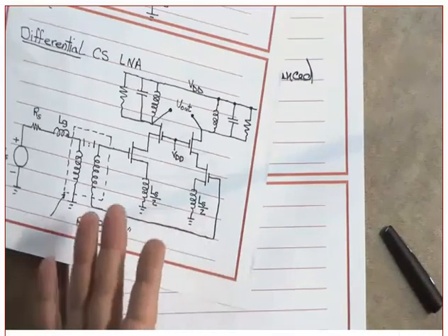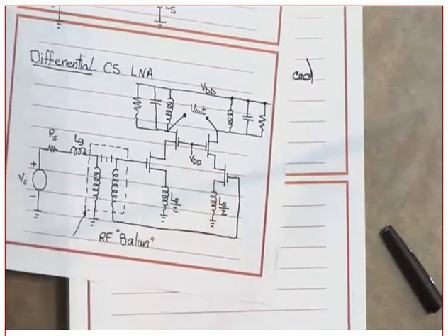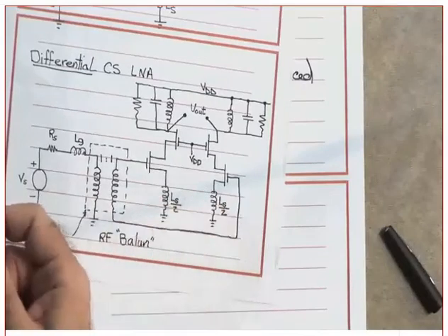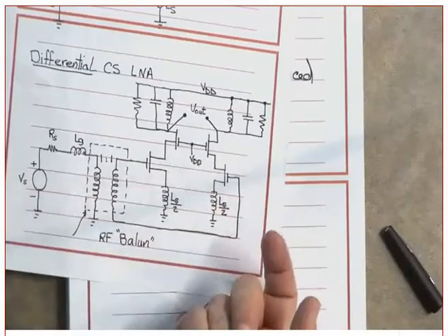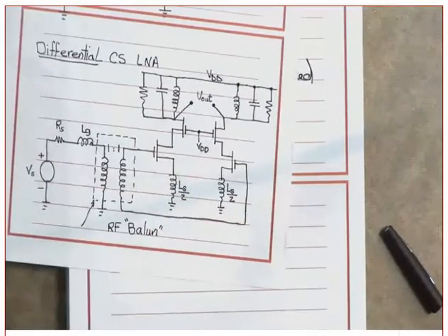However, you need to understand one thing, is that when you design your amplifier as a differential pair, it first of all will take more space. And there will be also more power dissipation because you are using two transistors instead of one. So all of these needs to be traded. Are you following me? Now, some designs use what?